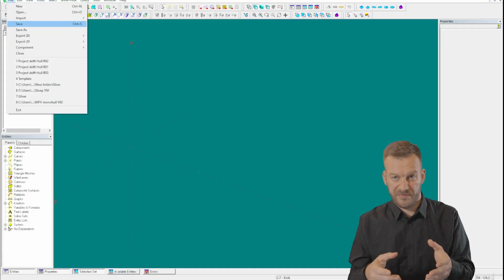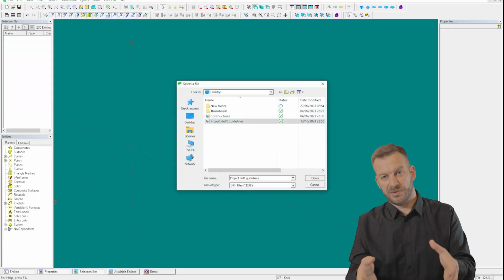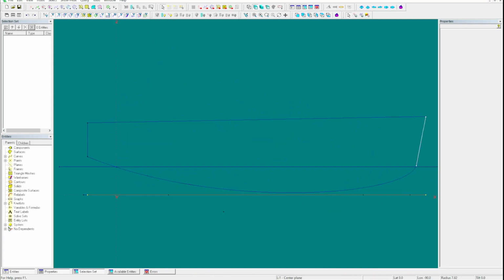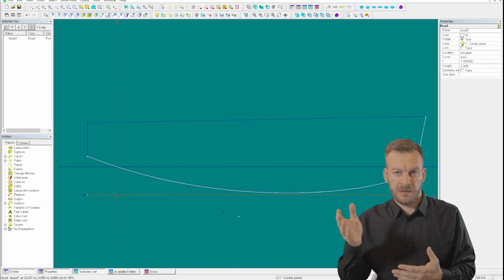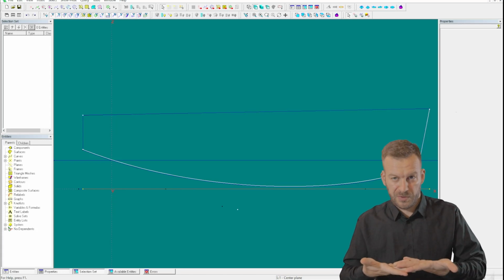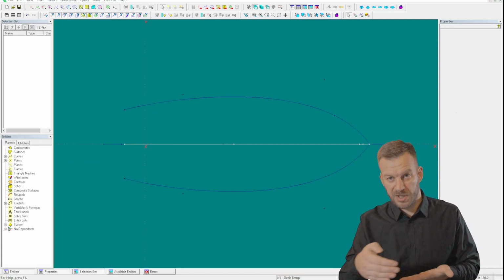Now when we have a DXF file, I will import that file into the hull tool and start creating new lines. This time I will start with the center plane, so I will have 2 points and a line to make a bow stem, then additionally 3 points to create the keel line. When that is finished, I will transfer into the floor plane and create the shear line in it.